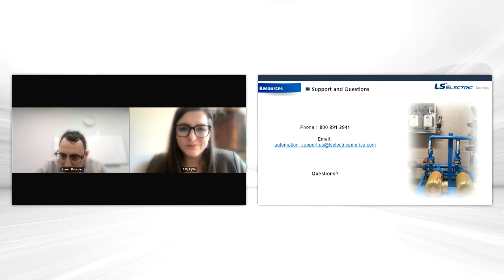So the big thing is you would need a sensor. The way they detect water level is they'll either use an ultrasonic sensor at the top, or a pressure sensor at the bottom, because water pressure weighs a certain amount. I forget what the formula is for PSI to feet. So you need that sensor on there, and then you could decide if you're going to do that as an auxiliary loop, or if you're just going to do dedicated water level. But it would probably be an inverse PI setup.